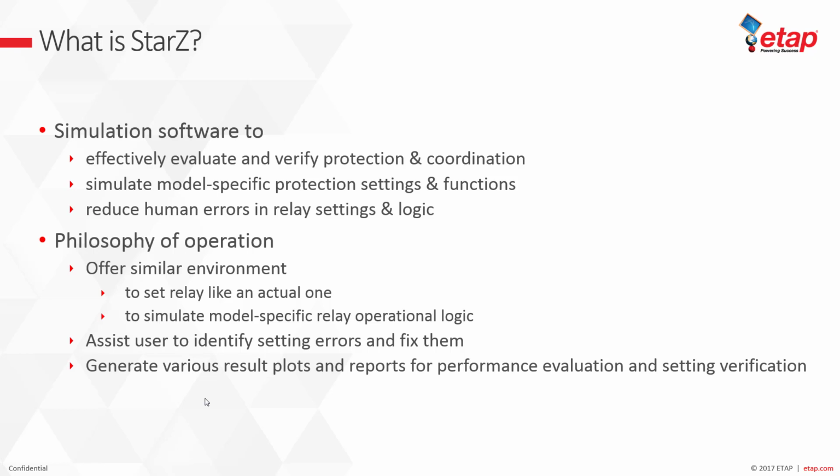This means that, as we will see in the demonstration and later in this presentation, in ETAP the user encounters the same settings and protection element outputs as the actual relay. Also, the modeled relay in ETAP performs similarly to the actual one for steady-state analysis supported in this module.